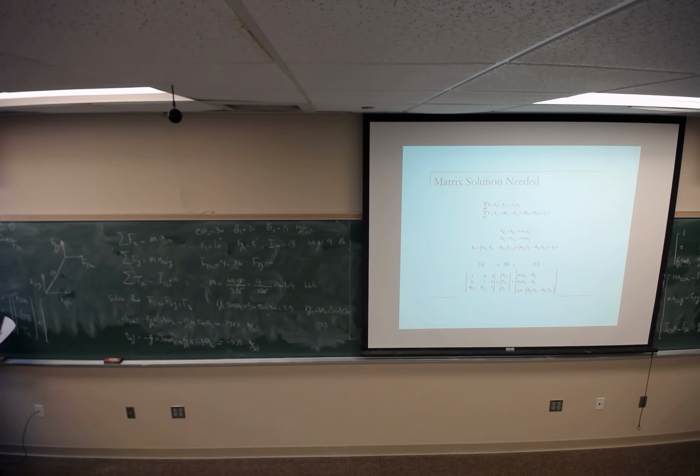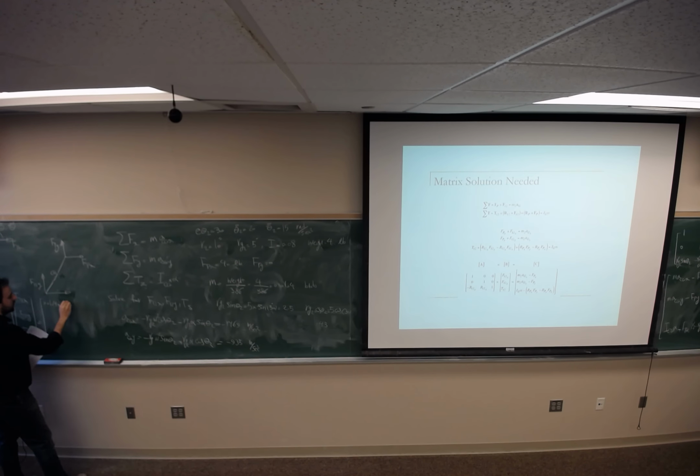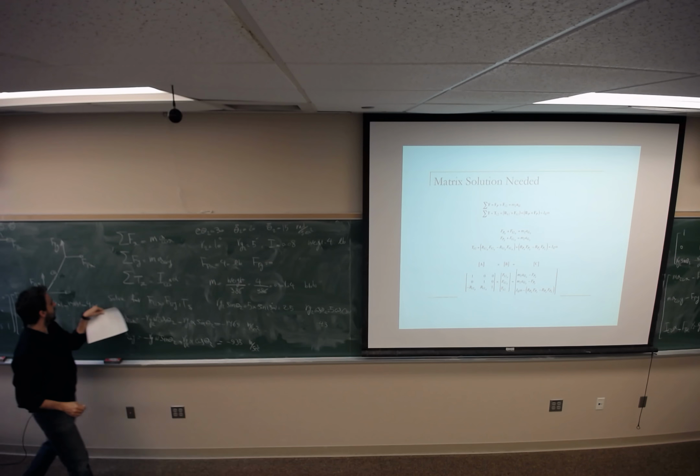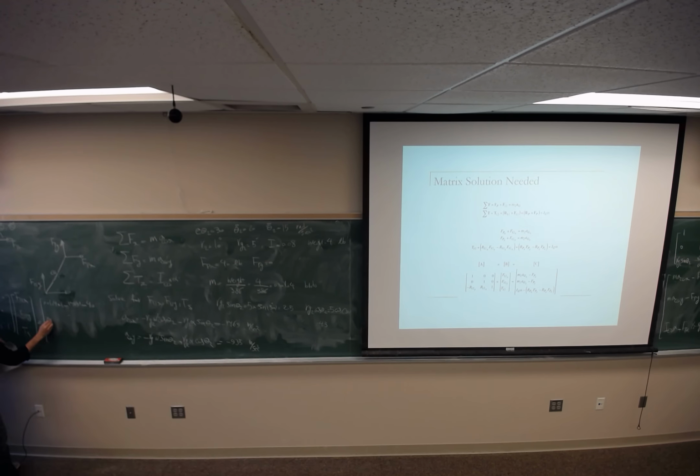On the right hand side, mass is 0.0104 times acceleration in x direction, negative 1769, minus Fpx. Fpx is 40 pounds, so negative 40. The second one is going to be 0.0104 times negative 935 minus 0.